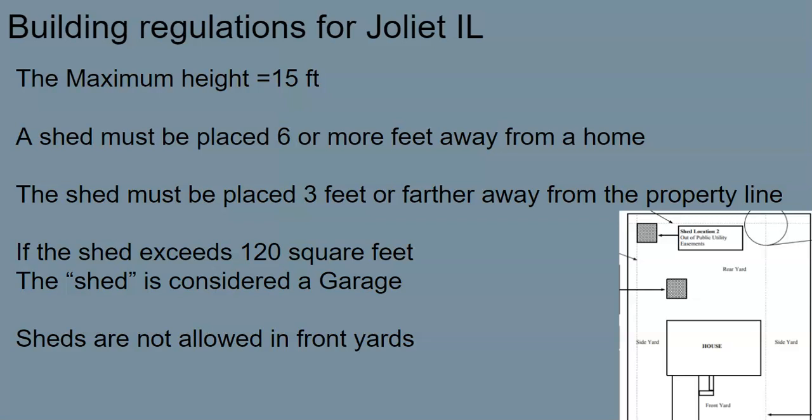The shed must also be placed 3 feet or further away from the property line. If the shed exceeds 120 square feet, it is now considered a garage. And in the city of Joliet, sheds are not allowed in front yards.